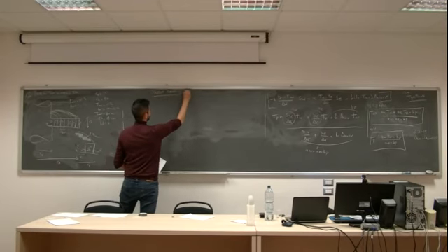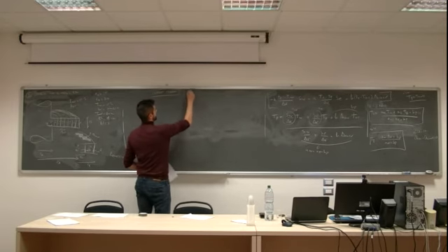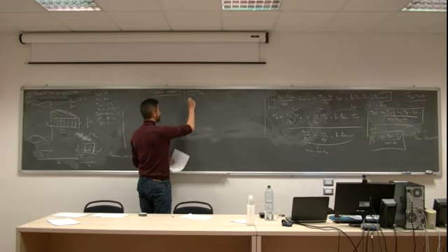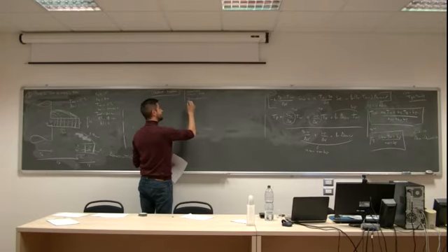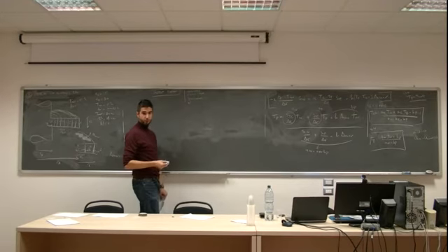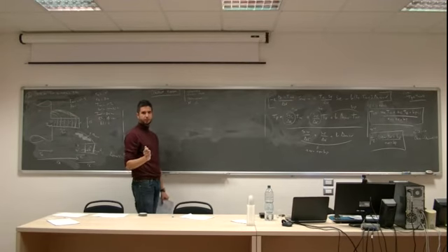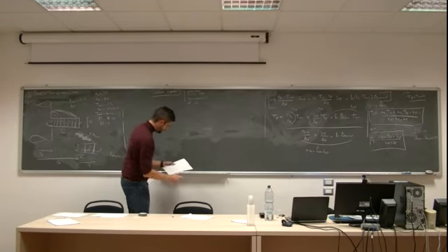Here you need to add geometry, physical properties, boundaries, and two values. One is n, the number of nodes that you want to use, and the other one is this delta, which is the error that you can accept. Now we will see where the error is. Okay?